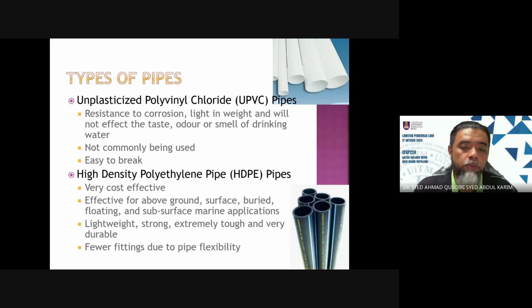It is not a problem because these HDPE pipes are also very light. Okay, so lightweight, strong, extremely tough, and very durable. It does not have an issue with problematic soil if you need to bury it, like acidic soil and those kinds of things. No problem for the pipe.